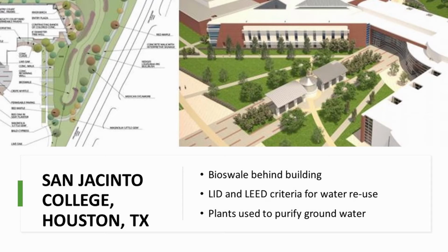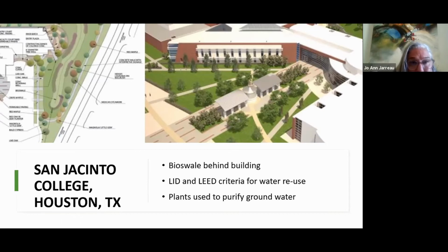Well, actually I would do the area. We work back and forth. So I would allocate the area, and then depending on how deep it would be, our cross sections would be determined by the civil engineer on how much water it needed to hold or convey. So it was a combination of the size of the pipe, the width of the bioswale, the depth of the bioswale, and the area that it was draining. It was all a calculation that we went back and forth designing until we got the right formula.